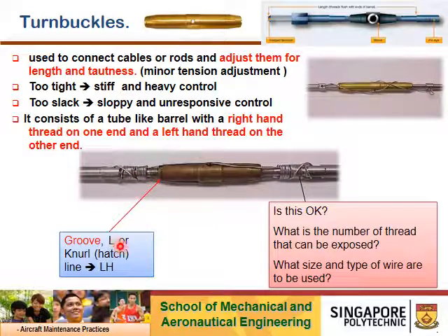Okay, the difference between left and right-hand thread: to tighten or to engage, you need to turn anti-clockwise. It's opposite of right-hand thread. Okay, one thing to consider after you engage the whole system: how many threads can be exposed, and what is the safety lock wire size to use. All this will be taught during the practical. All right.